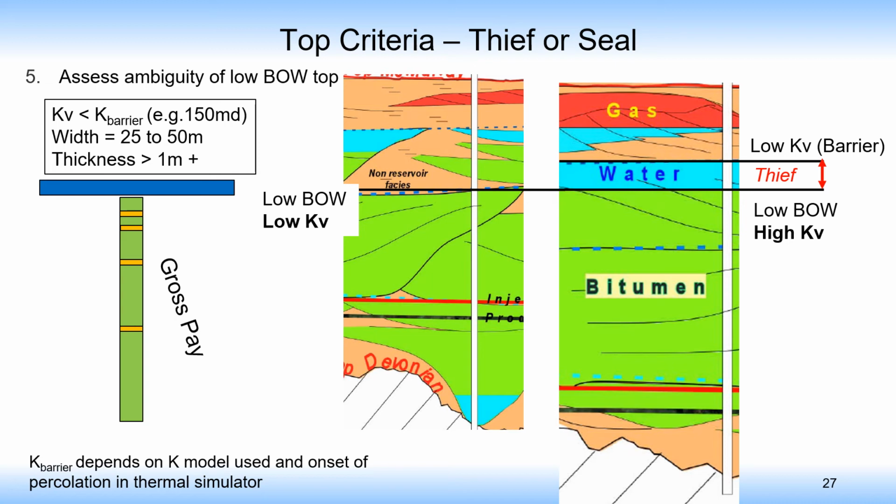We also look at this as a lateral block, whereas the other was columns. We need to look at adjacent cells, at least 25 meters up to maybe 50 meters. You could go up to 100 if you want, but you're going to have a hard time in a stochastic model going above 50 and finding something. So we set this thickness to about 1 to 1.5 meters, and it has to be this entire block of low vertical perm.